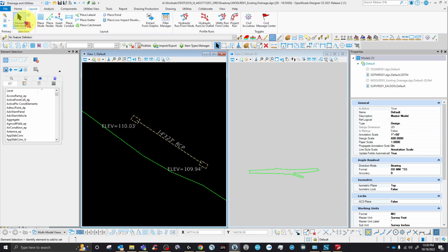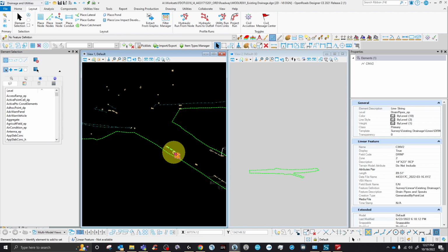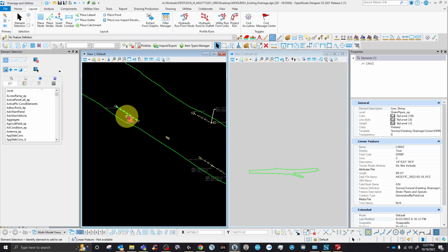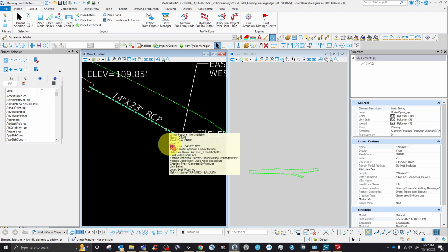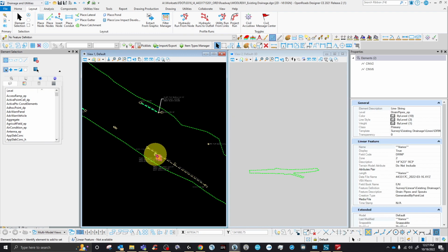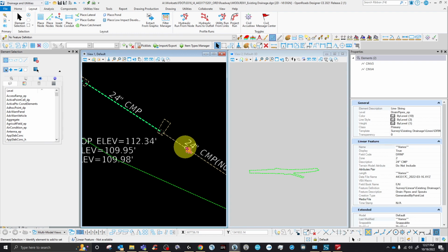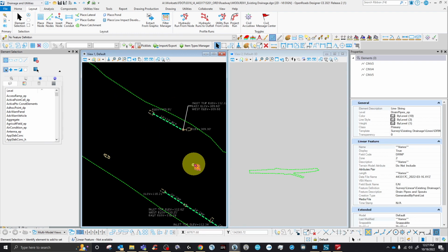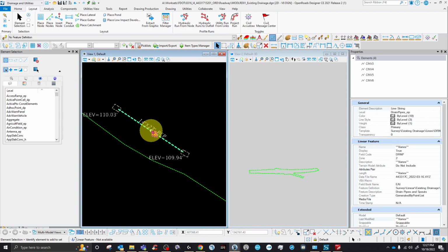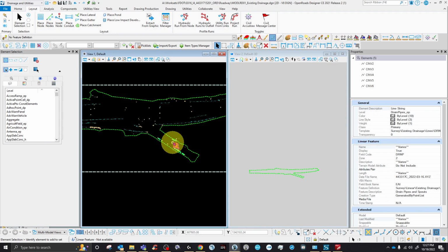Yeah, I just clicked exit, because what I like to do is select it first. If you have RCP, you have another one here, I also select this while I'm holding the control button, because if I click this, it's going to unselect it. So let's select this one, and this one while I'm holding control. I want you to do it in one shot. It's up to you, it's just my way of doing it. So I select all these pipes and I'm going to model them.